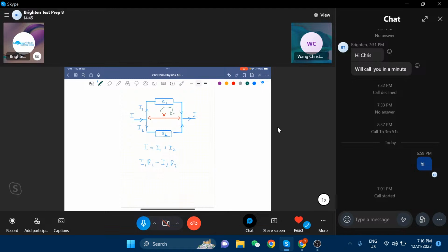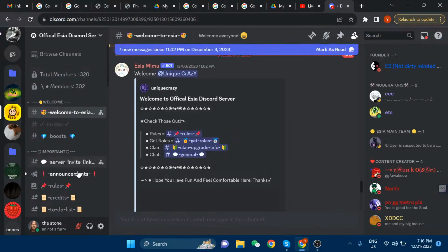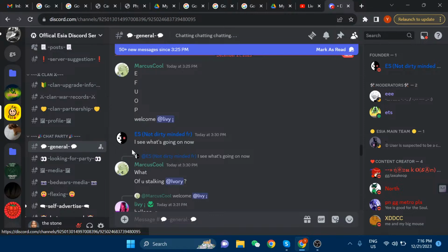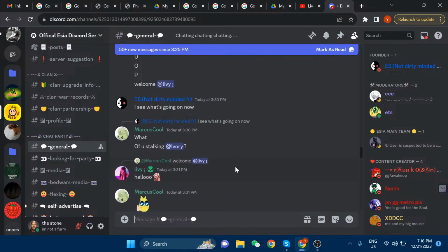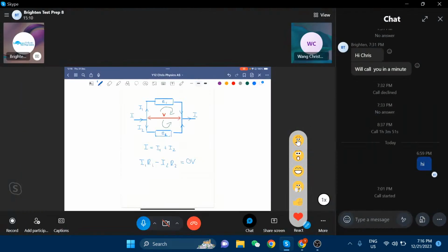It's always helpful to make the loop symbol. Say, okay, this one goes this way, this one goes that way. So clearly they're opposite. Just the visualization already helps. Then the second part is to say, okay, this is obviously the sum of the PDs, even if it's minus, that doesn't matter because it's a simple direction issue. And that is actually 0 because there's no EMF. The sum of the PDs must be 0 because there's no EMF, which means in consequence that they have to be equal. That's actually the whole secret, so to speak.